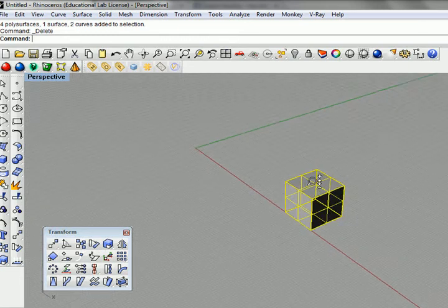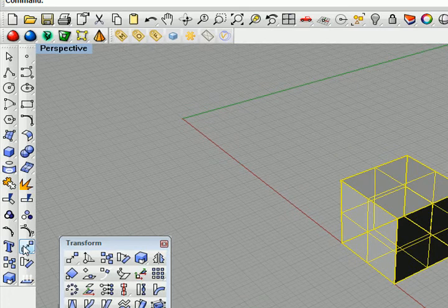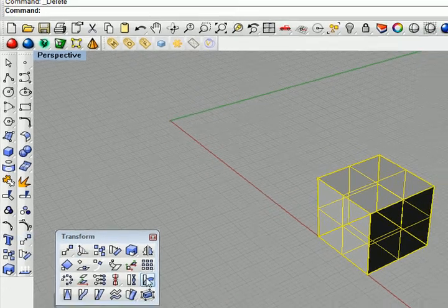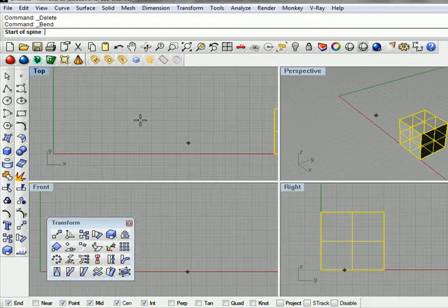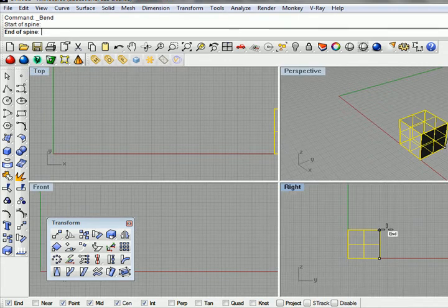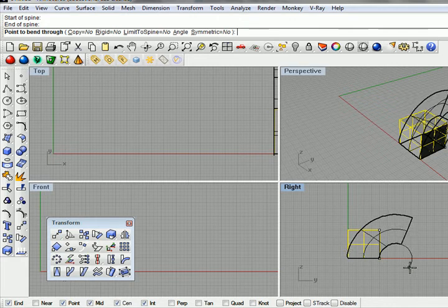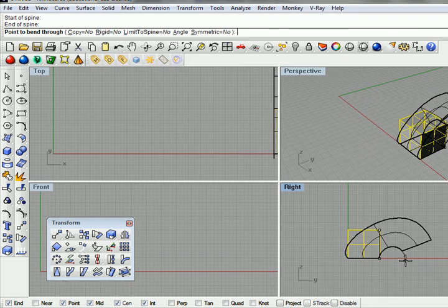And then the last function we have here is the bend tool. We'll take this guy, that's located right here also underneath the move tool. So we just click bend. And for the bend tool, we define a spine for this thing to be bent about. And then we can literally start to bend that geometry. And it wants to do this always on a circular arc here.